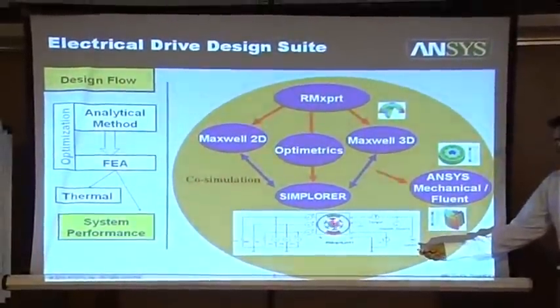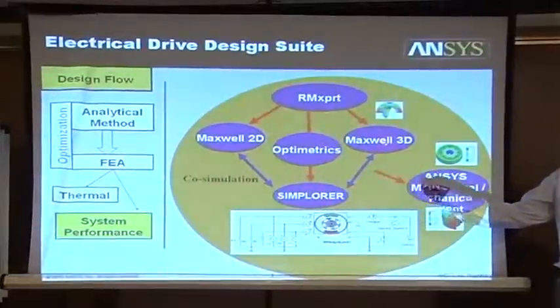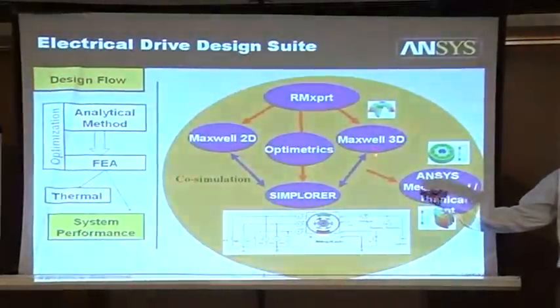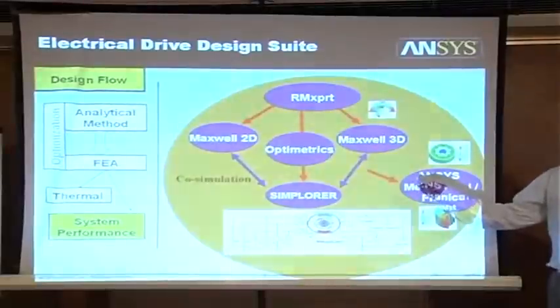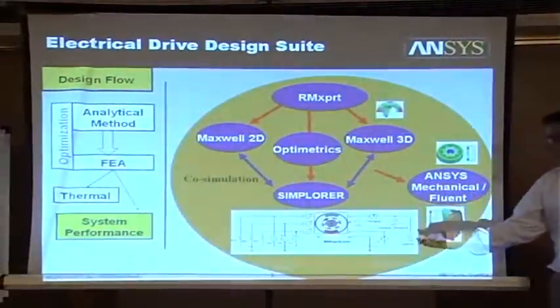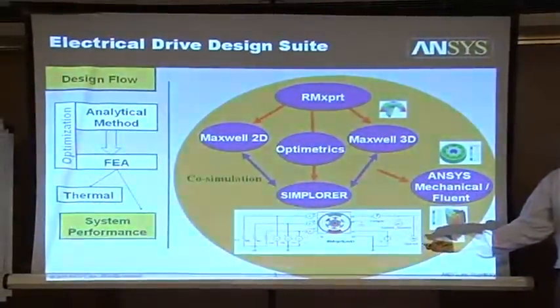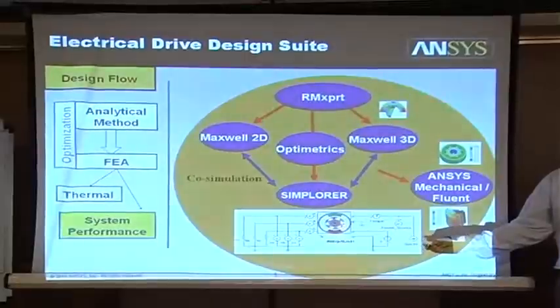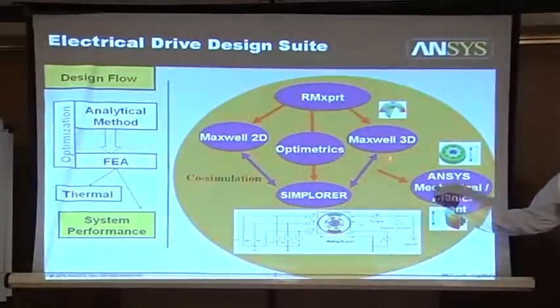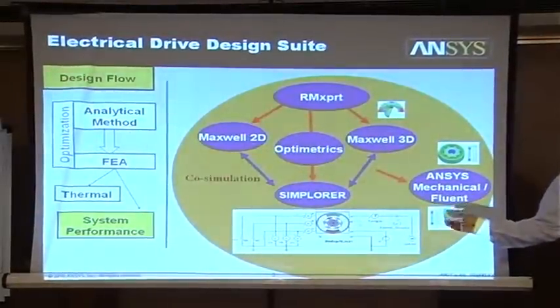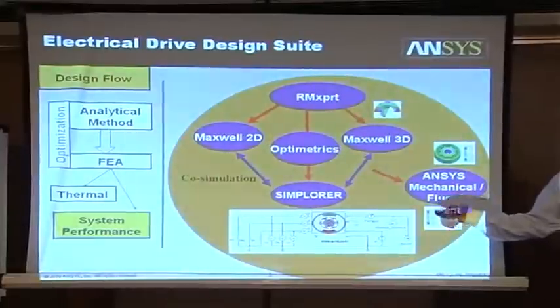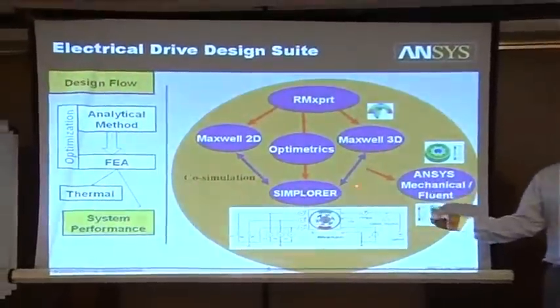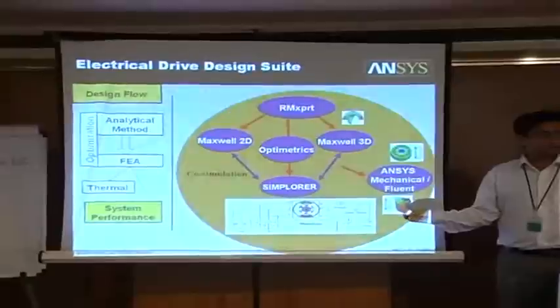This block will go back to the AC domain. At t equal to 1, this will be solved, the parameters will be extracted and it will be fed again to Simplorer. So this is dynamic, we are not assuming anything here, that L is constant, R is constant. All of those are taken as real time at t equal to 1.